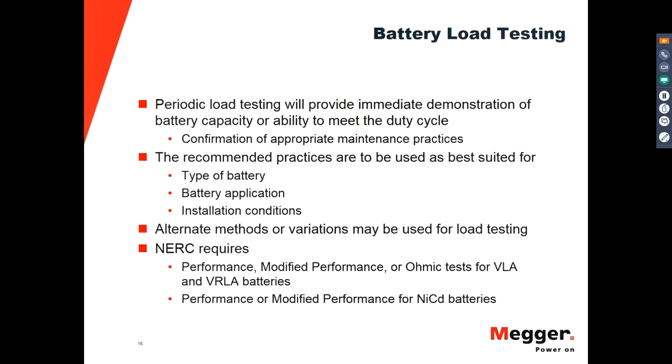Any periodic load testing will provide an immediate demonstration of the battery capacity or ability. You get the result, and you can use that to trend or to define some corrective actions. These recommended practices are best suited for different types of batteries, battery applications, and installation conditions.